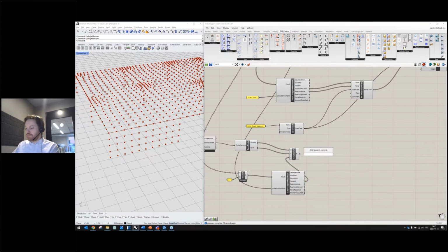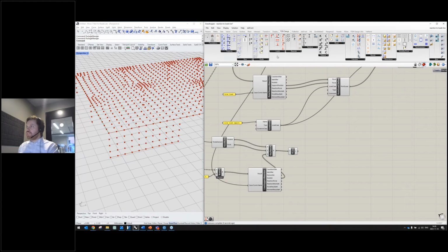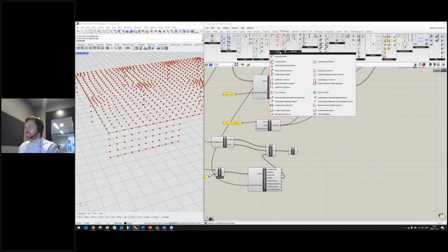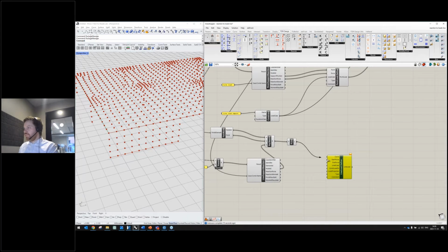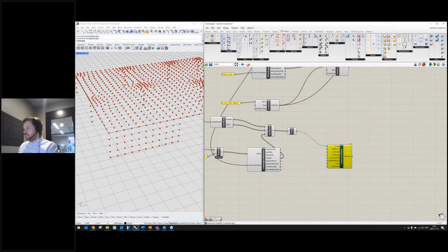And I can just create a line from this fit line. Yeah, here we have it. I can drag and drop, and I get a line over here. So let's create a line load. Let's go into loads, select the line load define, and I have the curve over here. Start and end force.